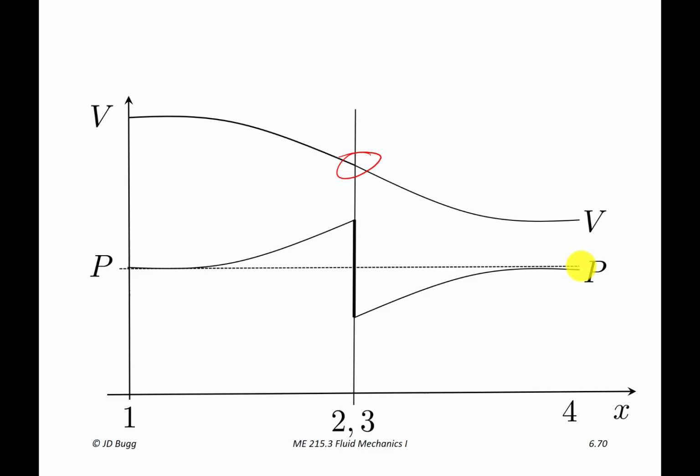Conservation of energy. So that means this pressure recovery that we see in the wake of the wind turbine causes a further decrease in velocity. So the velocity ends up dropping in front of the rotor plane and behind the rotor plane. And in fact, the analysis we just did tells us that the amount that it reduces in front is the same as the amount that it reduces behind.